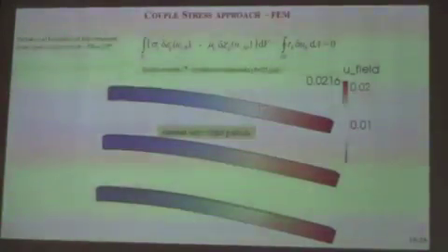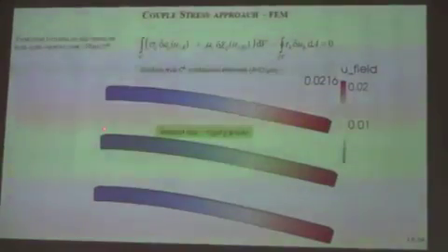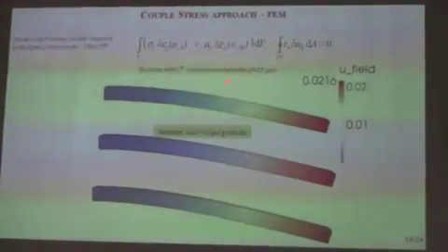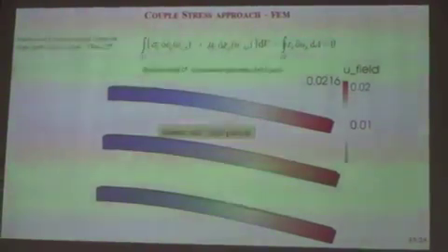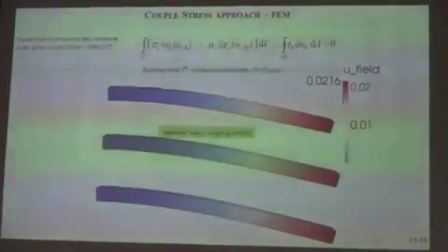And with this, I had to use, of course, C1 continuous elements. Okay, and I took a material length scale parameter that's quite big, so to say, 25 micrometers, but it doesn't matter for this point.